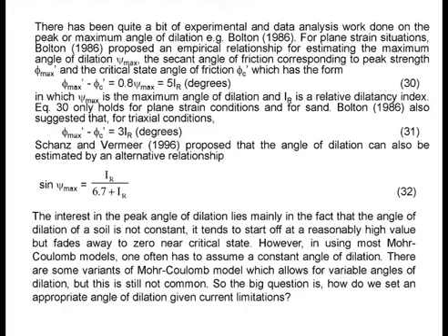Basically, as I mentioned to you, the angle of dilation is not a constant. So far, everything that has been done indicates that the angle of dilation is changing. And the thing that people have always investigated is not the angle of dilation, but the maximum angle of dilation. The maximum, all right? The maximum angle of dilation.